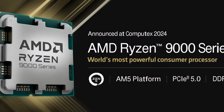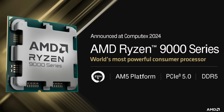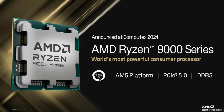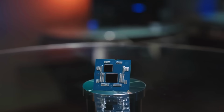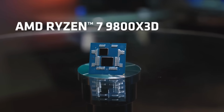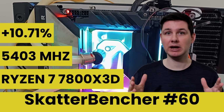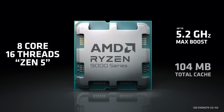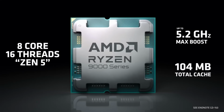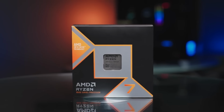The AMD Ryzen 7 9800X3D is part of AMD's Zen 5 based Ryzen 9000 desktop processor product line, codenamed Granite Ridge. The Granite Ridge processors were introduced on June 2nd, 2024 during Computex. The Ryzen 7 9800X3D succeeds the 8-core Zen 4 Ryzen 7 7800X3D, which we overclocked in SkatterBencher number 60. It has a base clock of 4.7 GHz and a listed boost frequency of up to 5.2 GHz. Just like its predecessor, its TDP is capped at 120 watts.